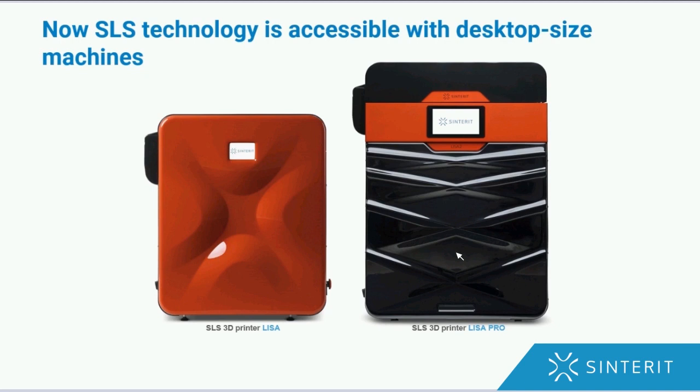In comparison, materials commonly used to print with any FDM printer have worse chemical resistances, and the same goes for materials used in SLA printing. FDM materials are temperature resistant, however SLA materials aren't. So these are the most important advantages that the SLS printers have over other 3D printers using FDM or SLA